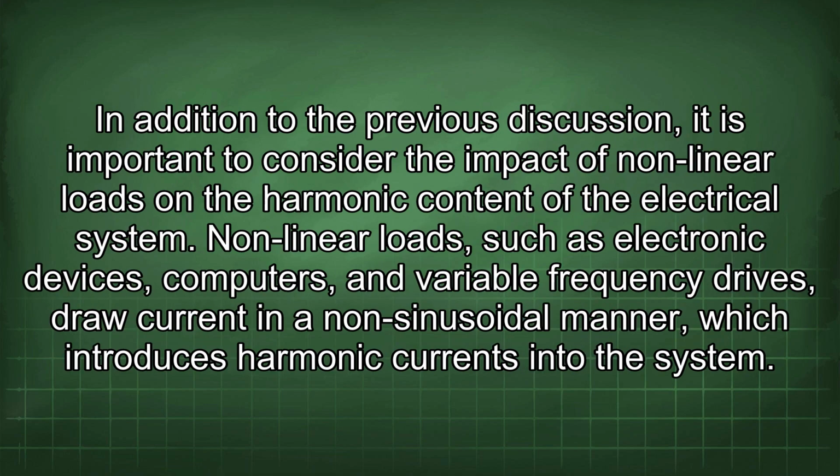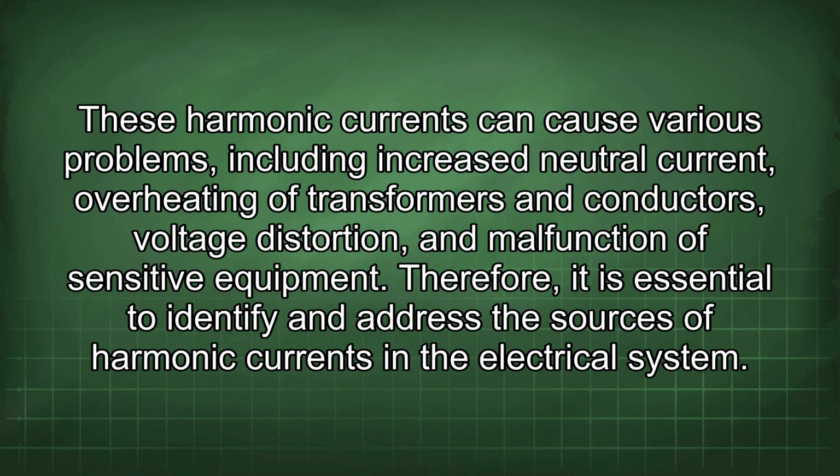In addition to the previous discussion, it is important to consider the impact of nonlinear loads on the harmonic content of the electrical system. Nonlinear loads, such as electronic devices, computers, and variable frequency drives, draw current in a non-sinusoidal manner, which introduces harmonic currents into the system. These harmonic currents can cause various problems, including increased neutral current, overheating of transformers and conductors, voltage distortion, and malfunction of sensitive equipment. Therefore, it is essential to identify and address the sources of harmonic currents in the electrical system.